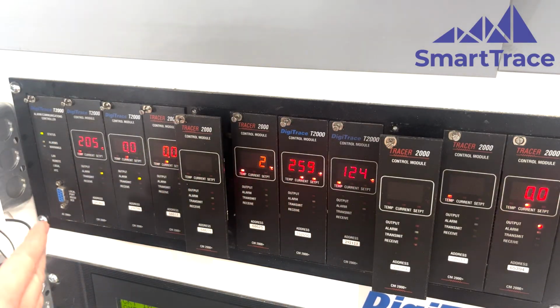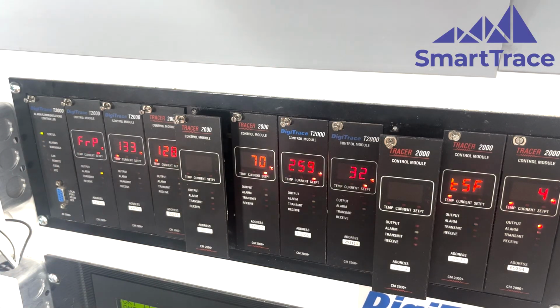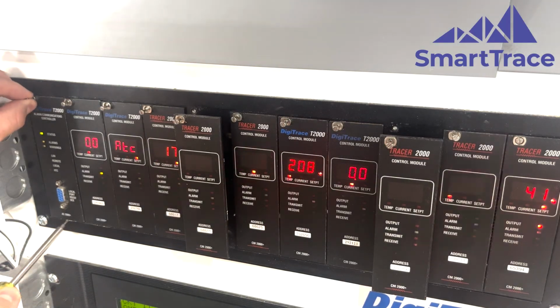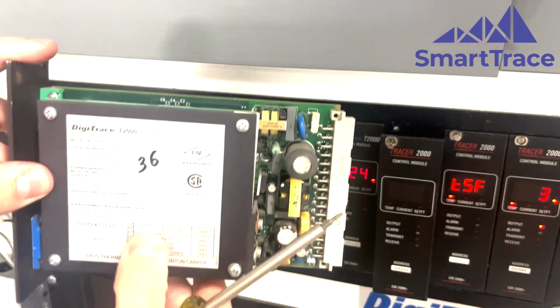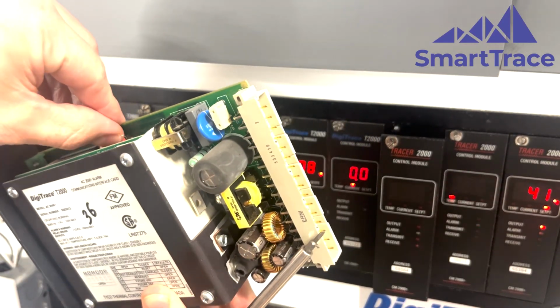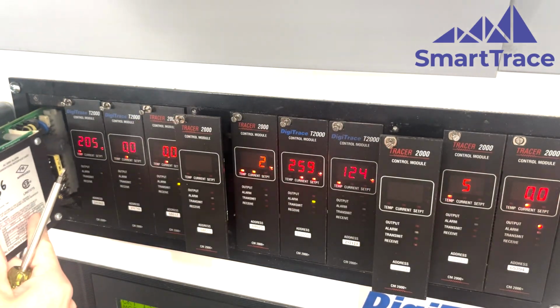When we first come up to this heat trace controller, we might not know the Modbus address or the Ethernet settings, but we need to be able to figure that information out. To do that, we first take the AC2000 card out of the rack, and inside you're going to see some dip switches. There is a little guide here, but dip switch 1 gives you the ability to put this module into config mode. So we're going to put this in config mode.